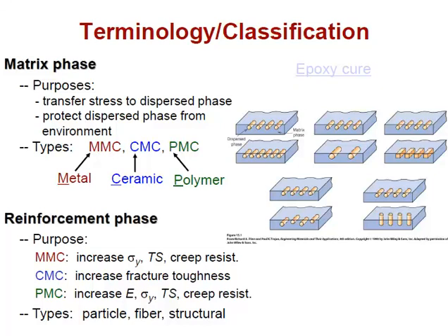So you'll add a ceramic or maybe a carbon fiber to increase modulus in one direction, to increase yield. Definitely if you include a refractory reinforcer in a metal matrix composite, you have the potential for improving your thermomechanical properties like creep and stress relaxation resistance.